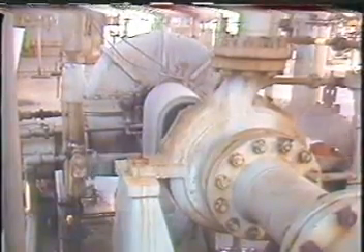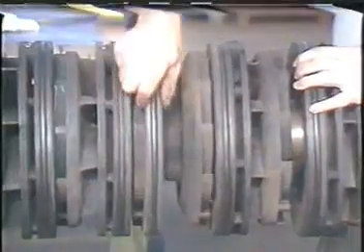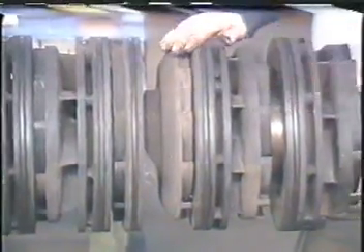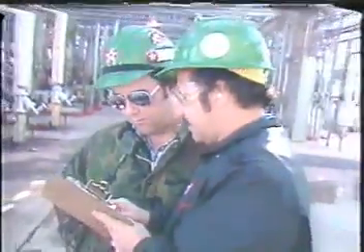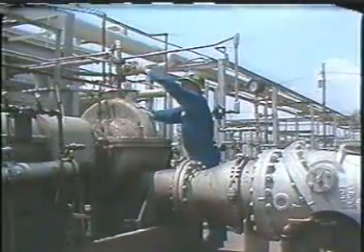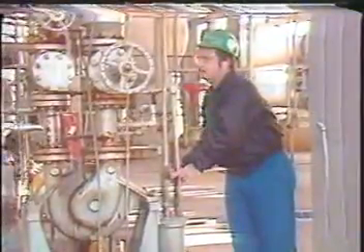In this program, you've learned how pumps add the energy necessary to move a liquid from one location to another. You also learned how certain pumps make use of centrifugal force to add velocity to a liquid in order to move it, and how various types of impellers and casings may be used in the design of centrifugal pumps. You learned the meaning of the term head as it is used in reference to pumping liquids, and how pump performance curves may be used to help set a pump to perform at its best, given other operating variables. Finally, you learned various methods of priming a centrifugal pump and why this is important, and some typical startup and shutdown procedures.